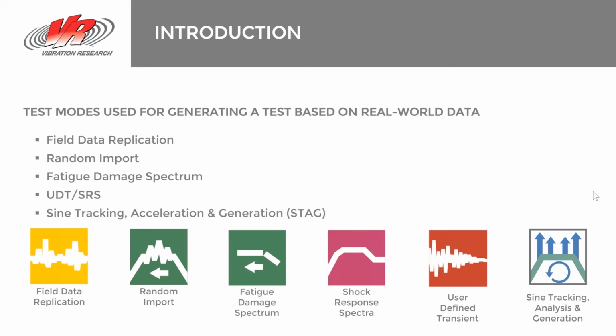The fatigue damage spectrum, there are a few methods that we will talk about, and we will specifically discuss the method that is implemented in VibrationView for analyzing a series of environments or a series of time history waveforms, accounting for the non-Gaussian nature by analyzing them in the time domain rather than the frequency domain, and then converting them into a fatigue damage spectrum where we can use that combined fatigue damage spectrum to appropriately weight different environments, and in the end, combine those environments so that we can generate a damage equivalent random PSD at the end.